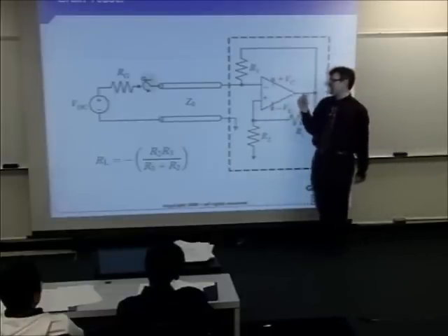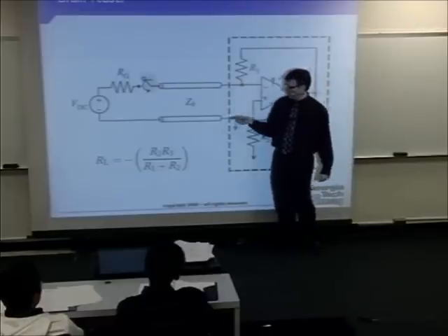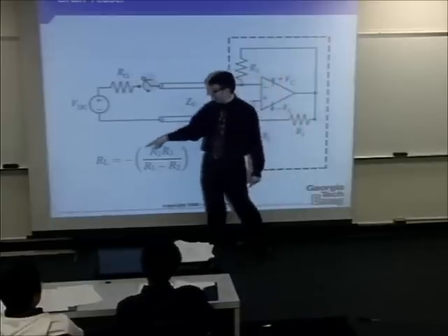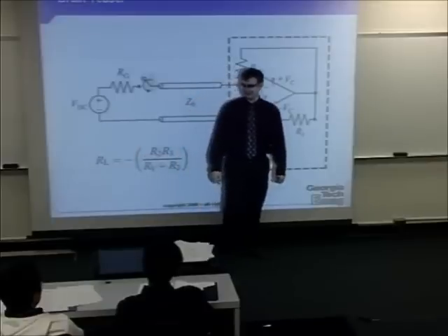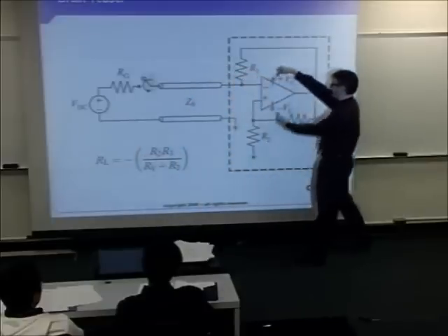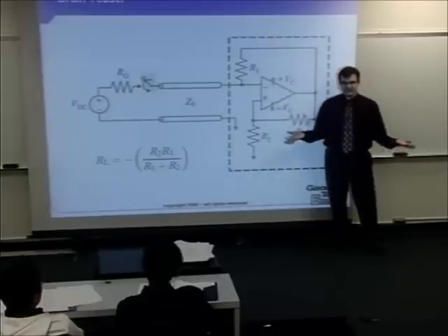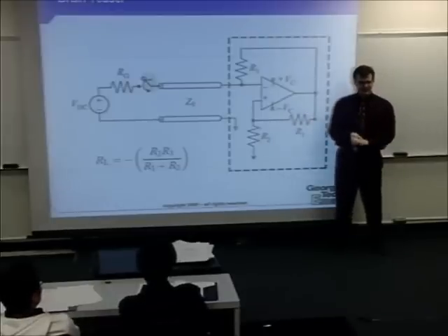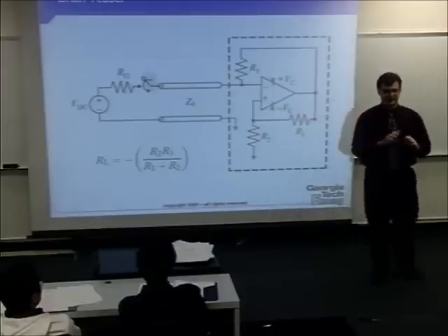When you calculate the Thevenin equivalent for this terminal, you get basically a single resistance value that is negative. Is that even legal? Well, of course it is. It's an active component. You got voltage power supplies here, so it can act like however it wants. You can often get transistors and biased semiconductor devices to act like an effective negative resistance. So here's a little brain teaser. What does that mean for the reflection coefficient at the end of the line?